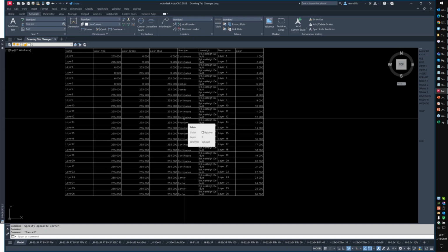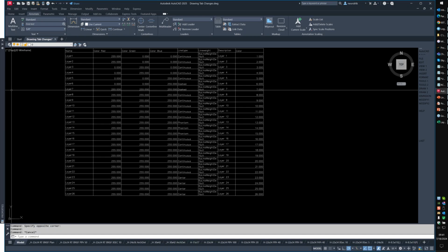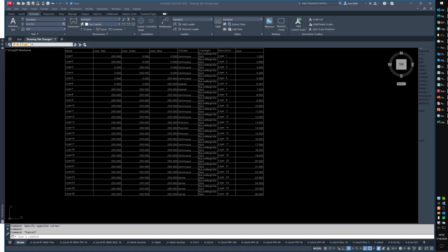You shouldn't have to. Can you import a PDF file into an AutoCAD drawing permanently so it becomes part of the drawing and not an xref? Now we're going to get into an interesting question. Jim, is the PDF a vector-based PDF or is it a raster-based PDF? If it's a raster-based PDF, you're not going to be able to permanently attach it without saving the PDF as a JPEG, copying it, and pasting it as an OLE object. That's the only way you're going to get a raster to be a part of the drawing.